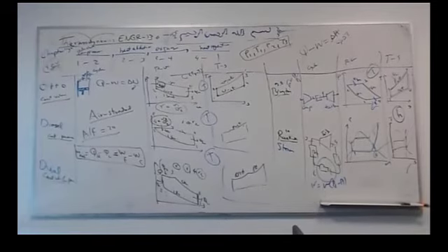So the higher T high is and the lower T low is, the better efficiency you always have. Always, for all the designs: Otto, Diesel, Dual, Ericsson, Brayton, Rankine, or any other cycles you have. Okay, guys? I wish that helps you to understand the cycles, which is the most exciting part in the course.